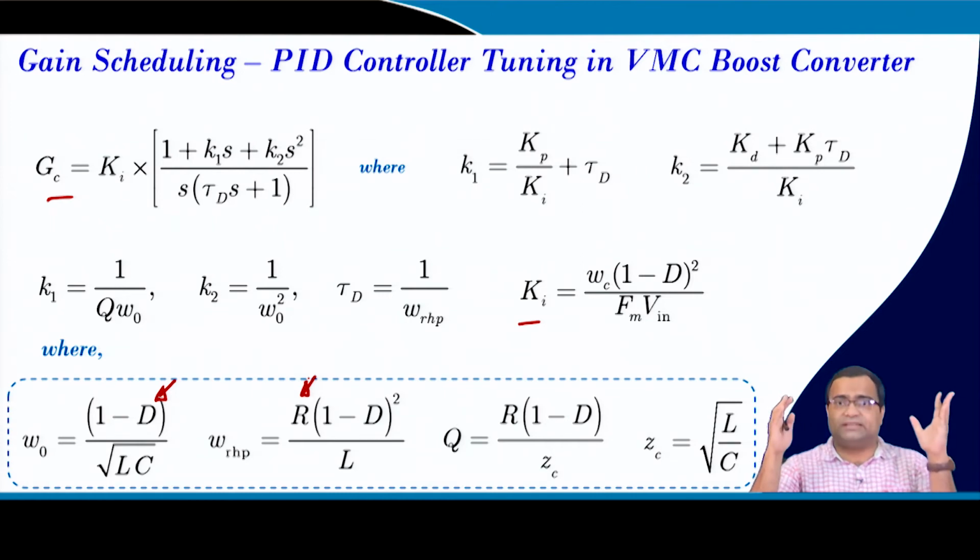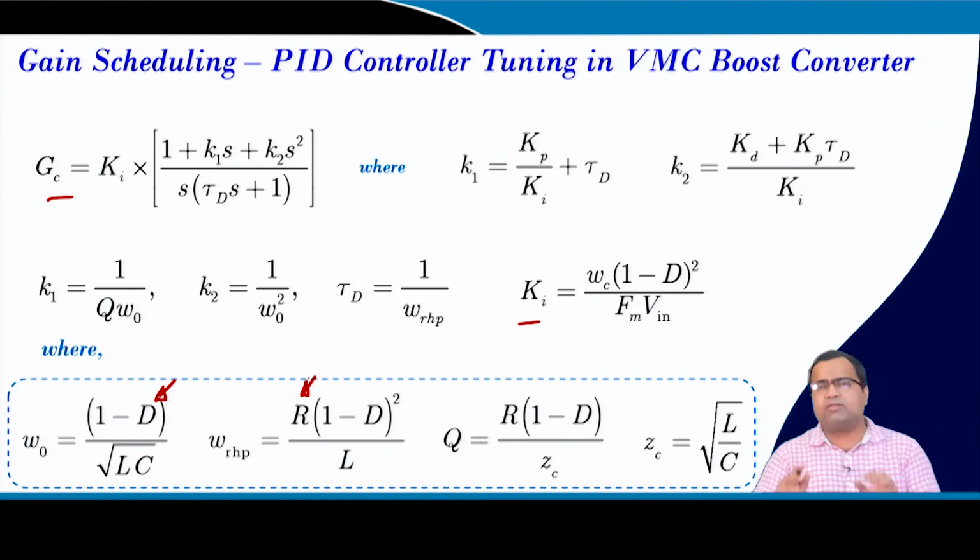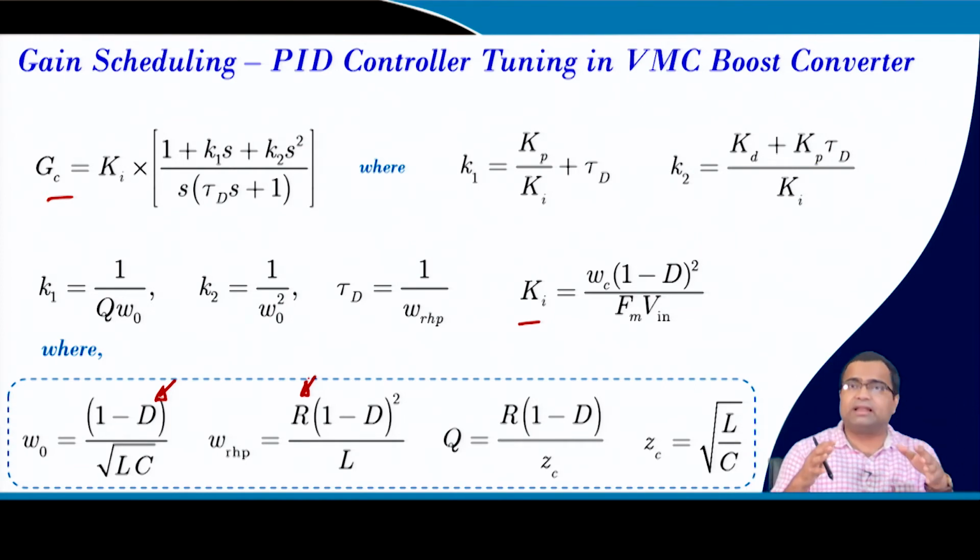So, this way we can get better response than fixed compensator based design. That means where you are fixing the compensator gain at the very beginning in analog control, where we do not have flexibility to change the controller value abruptly, because they are implemented off chip or outside using actual components, where changing resistance, capacitance, and all these values are really difficult. But once you plug into digital, where the coefficient is just a number, that can be updated by this method. So, this method can improve performance over the worst case design where the controller gains are fixed in analog control.